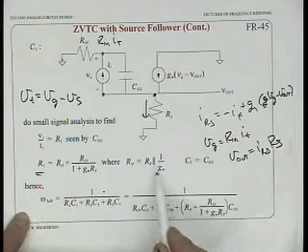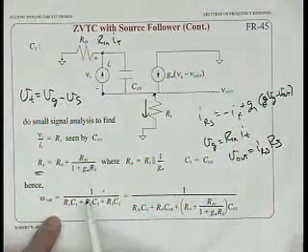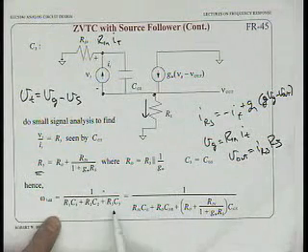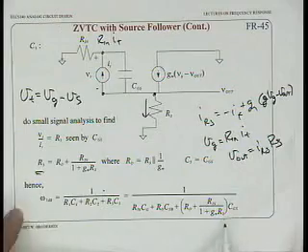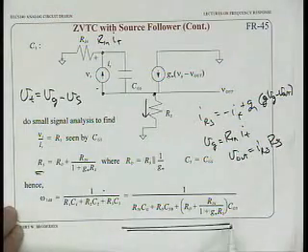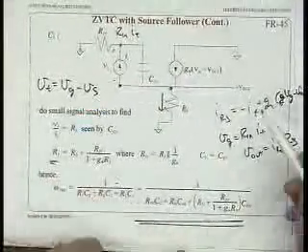And R0 is equal to RS in parallel with 1 over GM. So just solving this little problem right here. So I take the three time constants I just calculated, put them all together, and I end up with this is my answer. And is there any more pages? Is that all I did? Okay, well, I guess we can look at this.